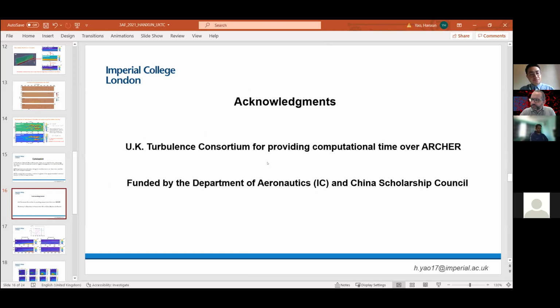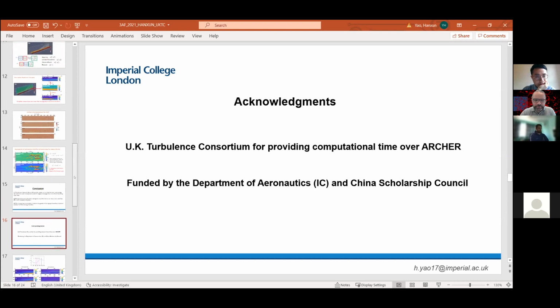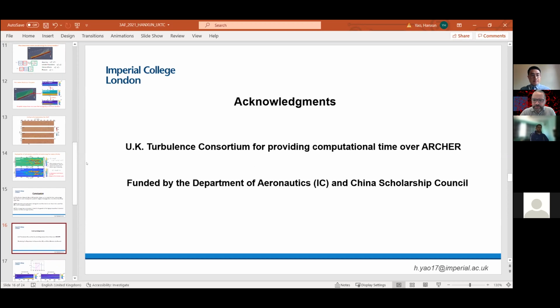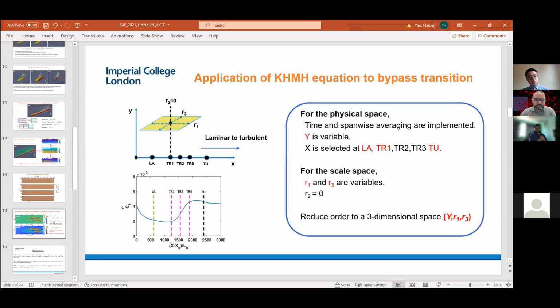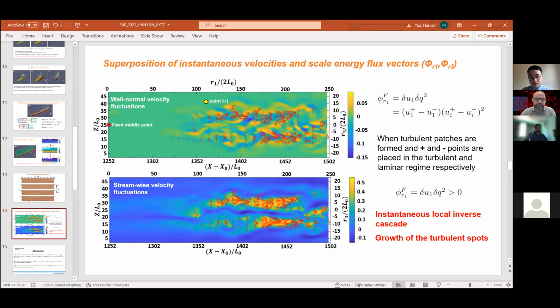The inverse cascade is energy at the small scale going to the large scale. So is it related to the small spots of turbulence that are merging together? So in this case, as I showed here, we showed only the results at the early stage of the transition, and the way we explain the inverse cascade is that the streaks of small turbulent structure are created during the transition by the mean flow, and also stretched out in the streamwise direction.